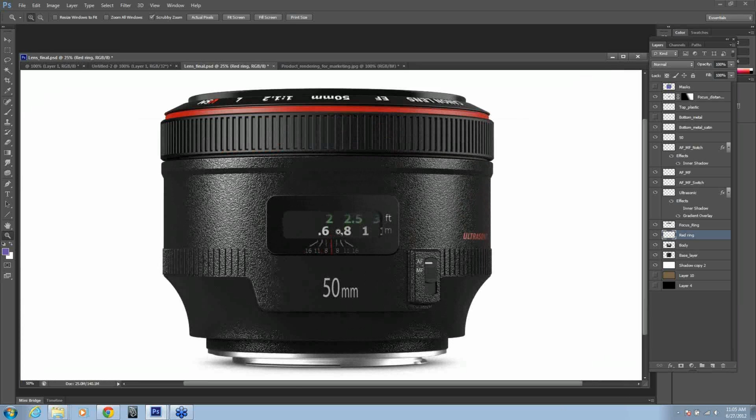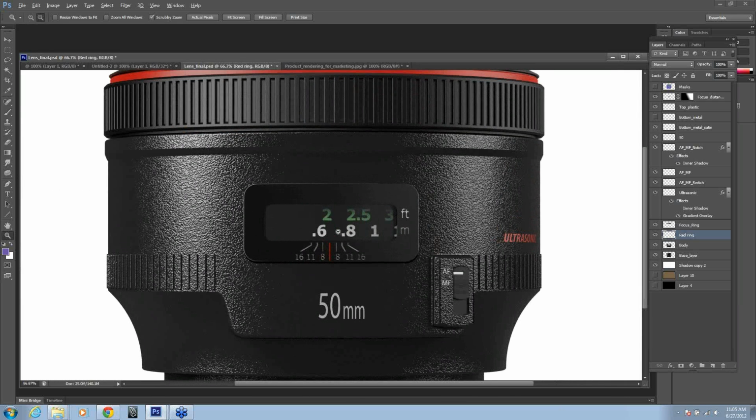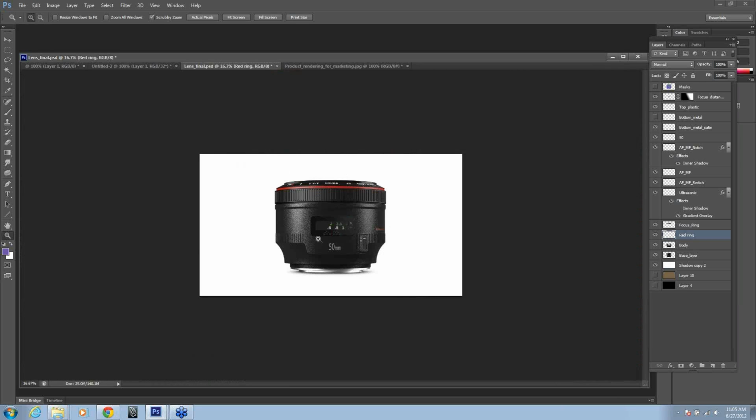Also, when you render images out at high resolution and then you scale them down, all that detail condenses down into the smaller image, and you get a much higher quality image. So even if I'm rendering something that's supposed to be a final image at this size, I tend to still do at least an image that's 4,000 pixels wide so that we can capture all this detail.